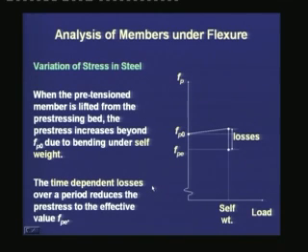Now, for a post-tensioned member, if the member is post-tensioned in the casting bed itself, then the self weight may not act during prestressing. But if the post-tensioned member is prestressed at the site where it is already being supported only at the edges, then the self weight is acting even before the prestress is applied.